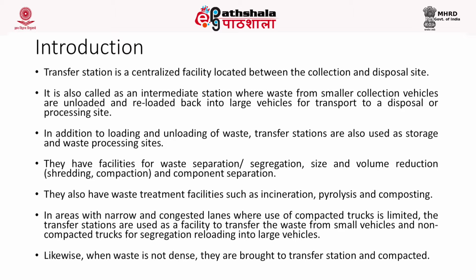In areas where you have a narrow or congested lane where you cannot use compactor trucks for waste collection, the transfer station can play a significant role in facilitating the transfer of waste from small collection vehicles to non-compacted trucks for segregation and reloading into large vehicles. Also, when the waste is not so dense, you can bring it to the transfer station and compact it.